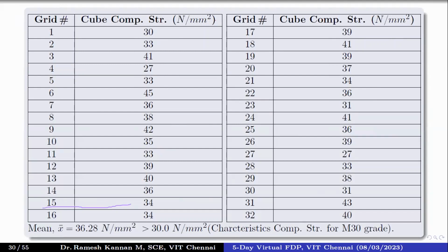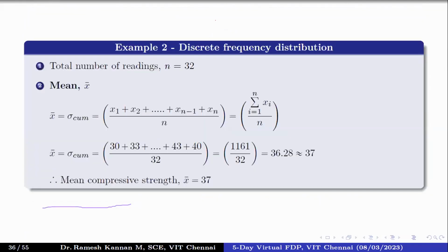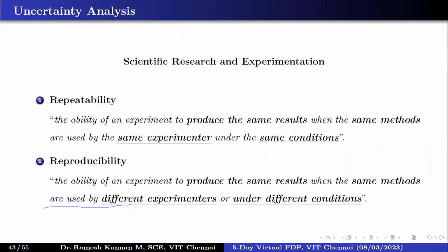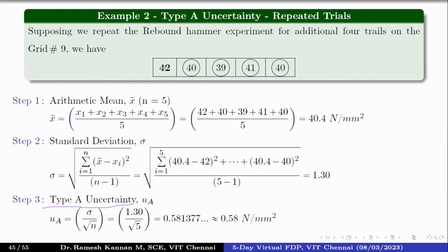With that, I cannot really conclude that this particular grid has a high compressive strength, right? So that will, in fact, change the average. If I include this in the average, and that in the other average, the entire average values get varied, and that's how we are lacking the true compressive strength, right?